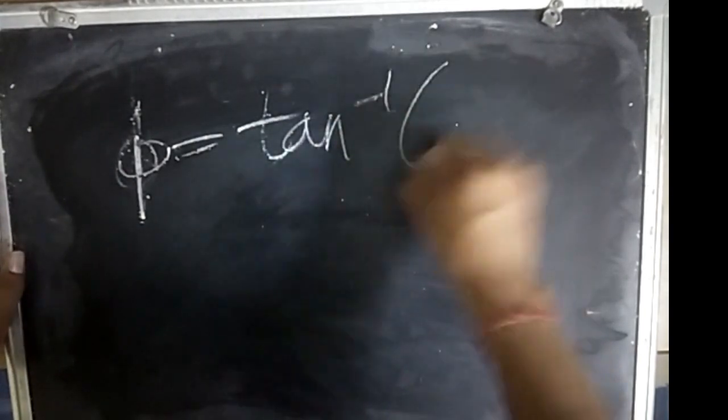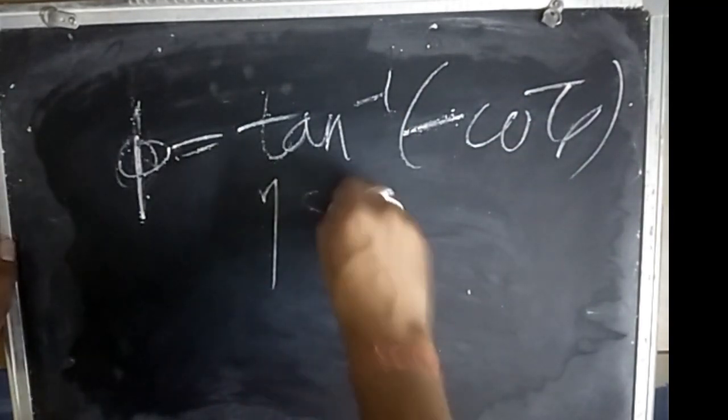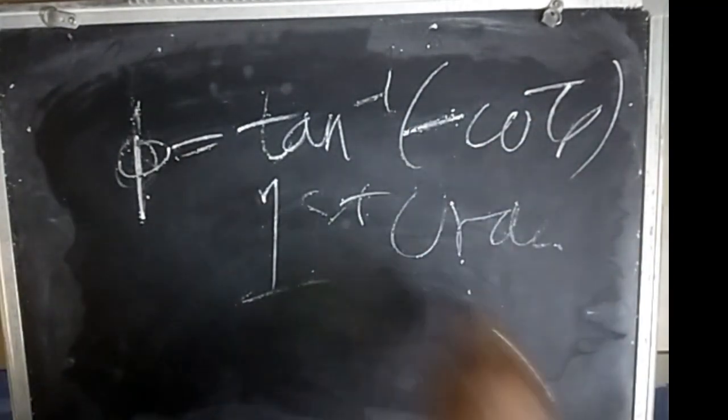So what are the different Bode plots for different systems? I've talked about that, and also this important thing is phi, the phase lag difference, which is tan inverse of minus omega tau p. Remember, this is minus omega tau p for first order systems.